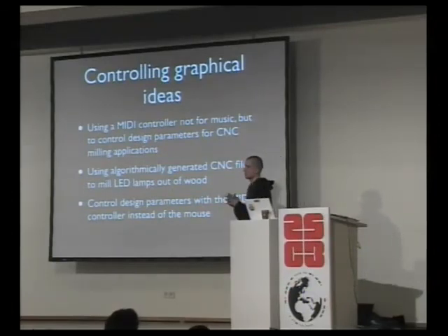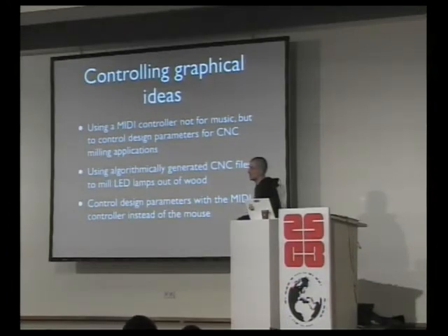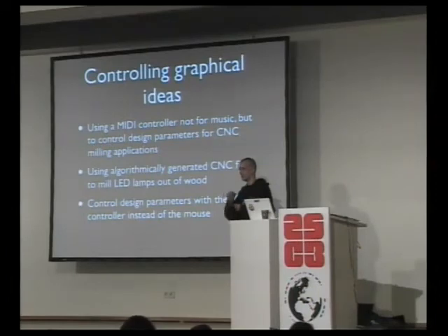So I use Processing to generate some kind of 3D scene and then convert that 3D scene to DXF and then import it into the milling application. And what I do is control the design parameters with the MIDI controller rather than with the mouse, for example. If you use the mouse, you would have to input some kind of control surface in Processing. It's all pretty annoying to do.